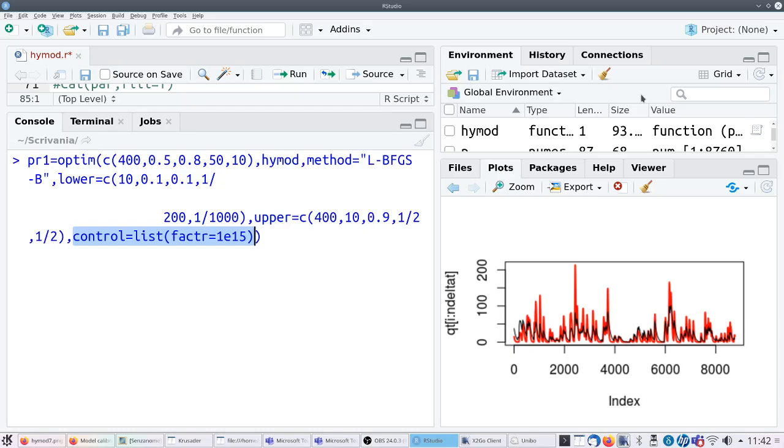This is the tolerance to reach convergence. And it's basically a stop criteria. We can tell the optimization procedure to search until a very precise convergence is reached, but this can take a lot of time, or we can reduce the tolerance to be faster. I'm not sure what is specified here is a good tolerance. Let's see. Let's run it.